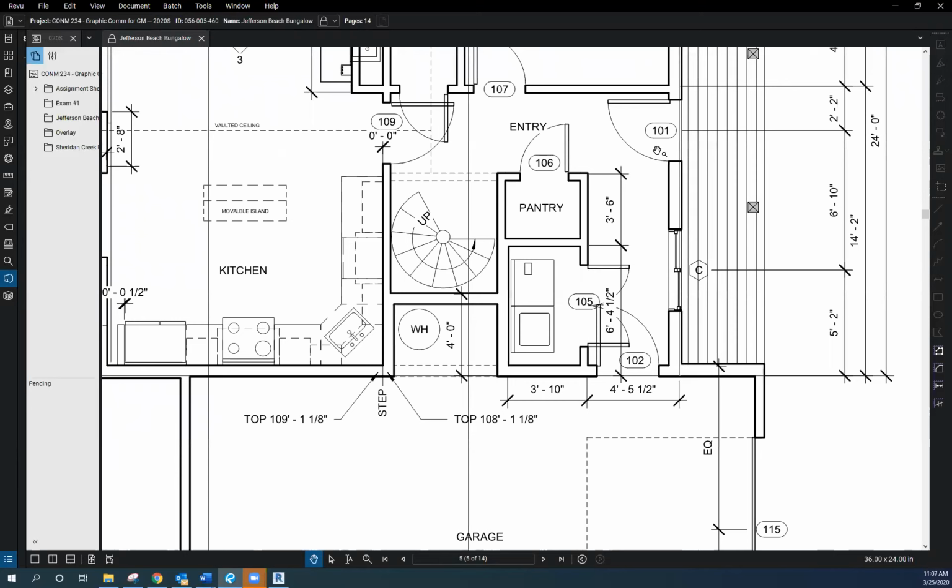In other words, this wall that we originally built was 1/2 inch drywall on the inside, a 5.5 inch stud, and then the 7/16 OSB and the exterior finish. That does not occur going along the wall from this point over to this point. In fact, as we look at this, this is what we may refer to as a wall type that we might call a garage common wall. It's a common wall to the house, to the garage.